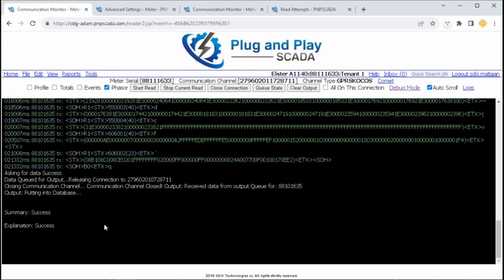It could happen that the system could not read all the data from the meter, but just a little bit of data. In such a case, the first stage will still show success, but the later stages will fail. So you need to see success on all stages before determining that the meter is reading.